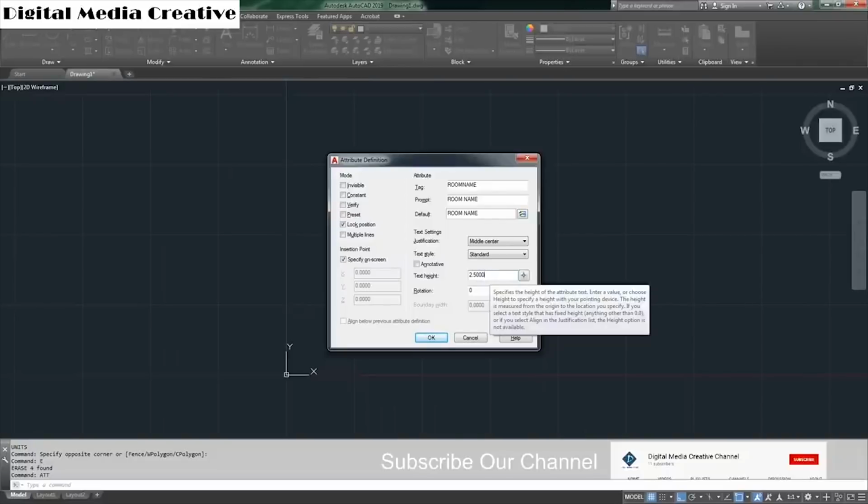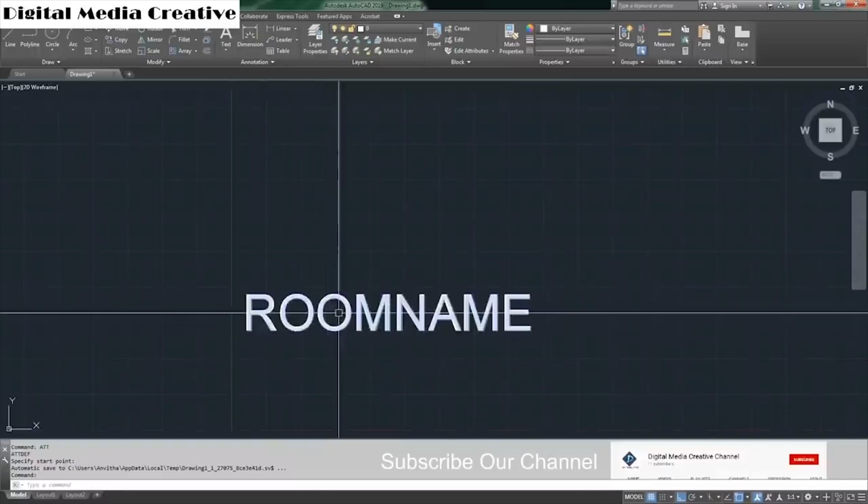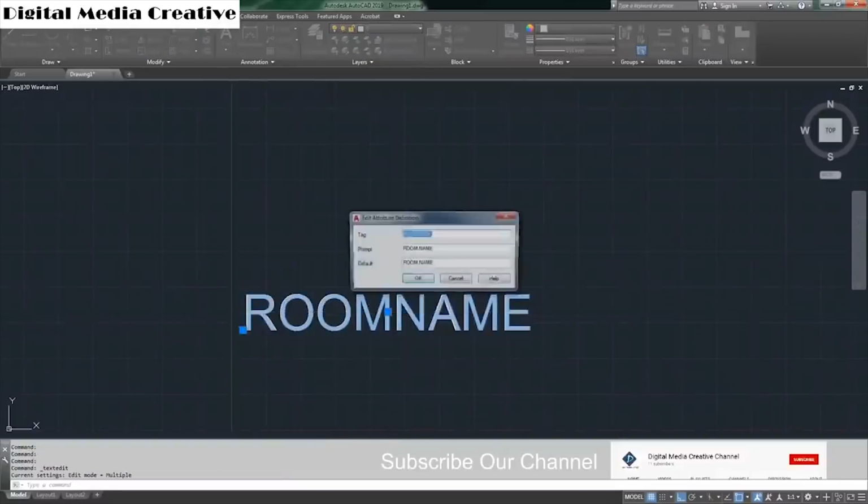So make sure you keep the text height as 2.5 because it's for 1:1 scale. And rotation, we don't want any rotation, so we keep it as 0. Just enter, then you insert the attribute. If you double click you can see the tag, prompt and default. Okay, it's a simple thing.